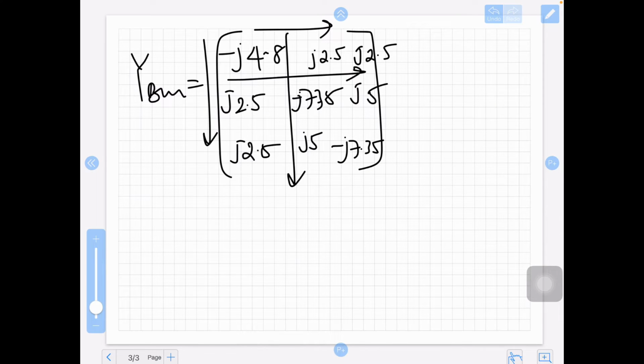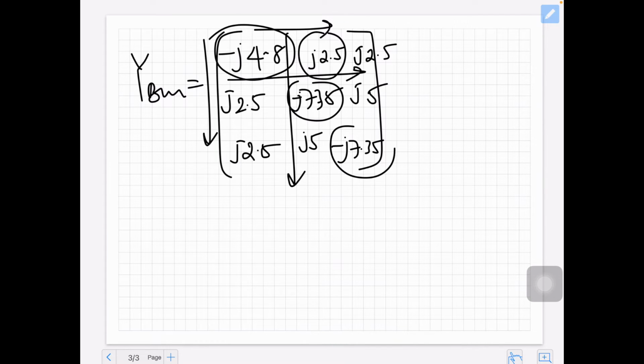You only need to find the diagonal elements and one side of the off diagonal elements. For all load flow calculations, one has to find the bus admittance matrix, which is very helpful in calculating voltages, real power and currents.